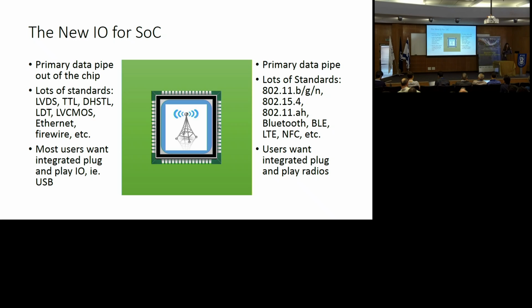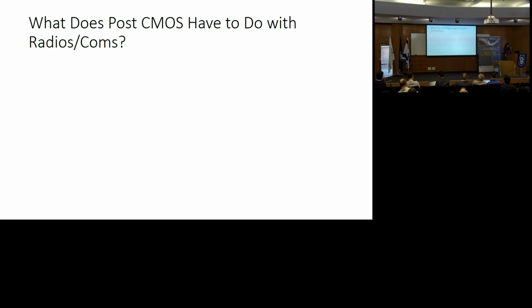So what does that mean? If everything's going to be connected in the wireless world, what does that mean for us? In terms of new devices, what can we do? On the receive side, we have an LNA, which is a low noise amplifier. We have an oscillator. There are advanced devices that can help with the design of LNAs and oscillators, but mostly very good switches aren't so great for this. So mostly we can benefit some from advanced CMOS processes because we get higher FTs, and we can certainly benefit from MEMS devices in terms of high quality oscillators, but most of the devices we've been talking about since we've been here don't help that much with these things.